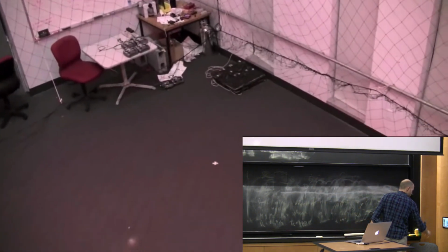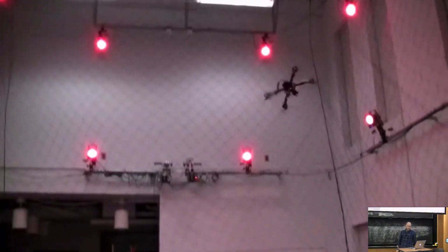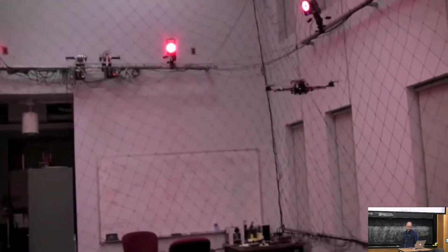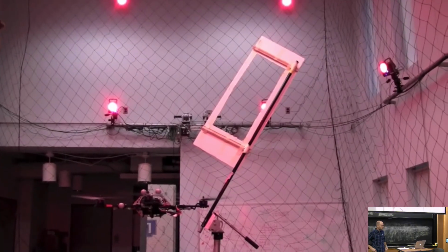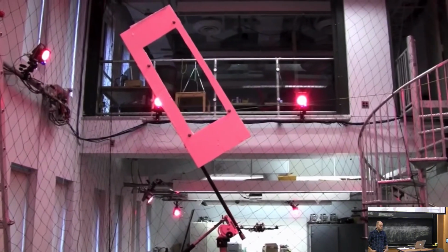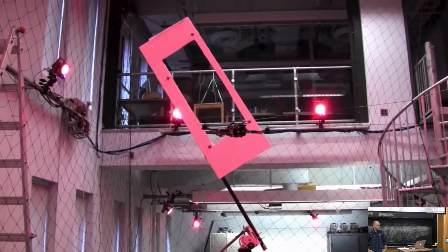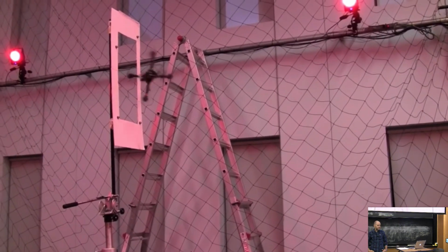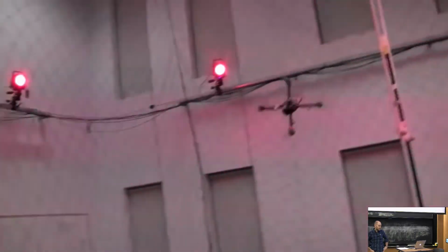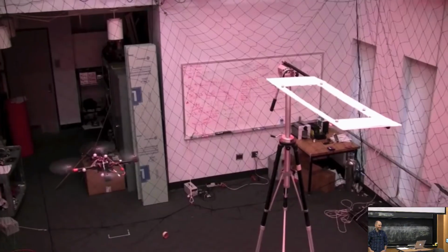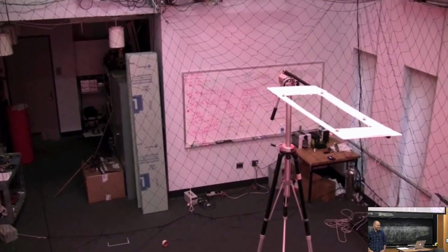This video presents autonomous control capabilities for a quadrotor helicopter. We use a 20-camera Vicon system and an onboard IMU for state estimation. Here we show single, double, and triple flips. We developed a method for flying to any position in space with any reasonable velocity or pitch angle. We use the method to fly through windows at various angles. Here there's less than 3 inches of clearance on all sides of the quadrotor. We also fly between other quadrotors. The same method can be used to descend or ascend through a horizontal slot.